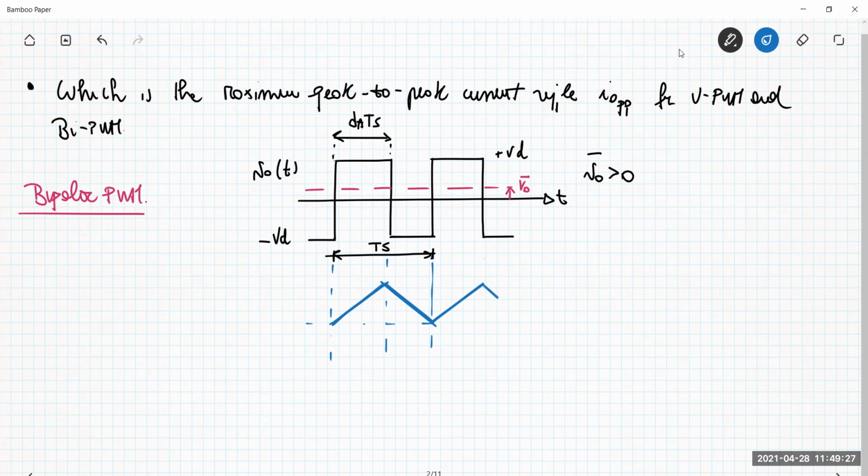Okay, so this is the current I naught versus T. This is just the ripple computation. Of course, this ripple is superimposed onto a pedestal, an offset, which is a DC current. Okay, is an offset above the continuous value. This is just a ripple component, because in this case I'm interested just in this peak-to-peak ripple, which is exactly this quantity.